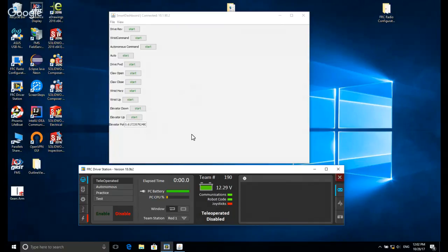The other thing you can do is if you're running CAN Talons, you don't actually need any fancy libraries. You just tell the CAN Talon, run this motion profile, and it'll just do it, which runs way better than running your own thing, unless you have to do something crazy like collision detection or linking multiple motor controllers together. That's the best way of doing it, because the CAN Talon can run the control loop so much faster than the RoboRIO can. But the Cross the Road Electronics guys are actually trying to make it so you can have a whole drive base and supply one motion profile for the whole robot to move in a particular way.